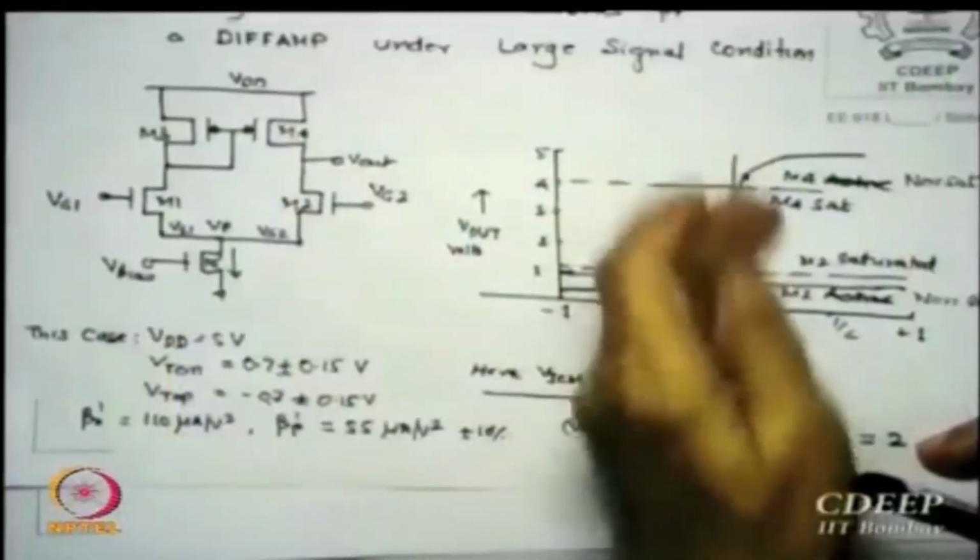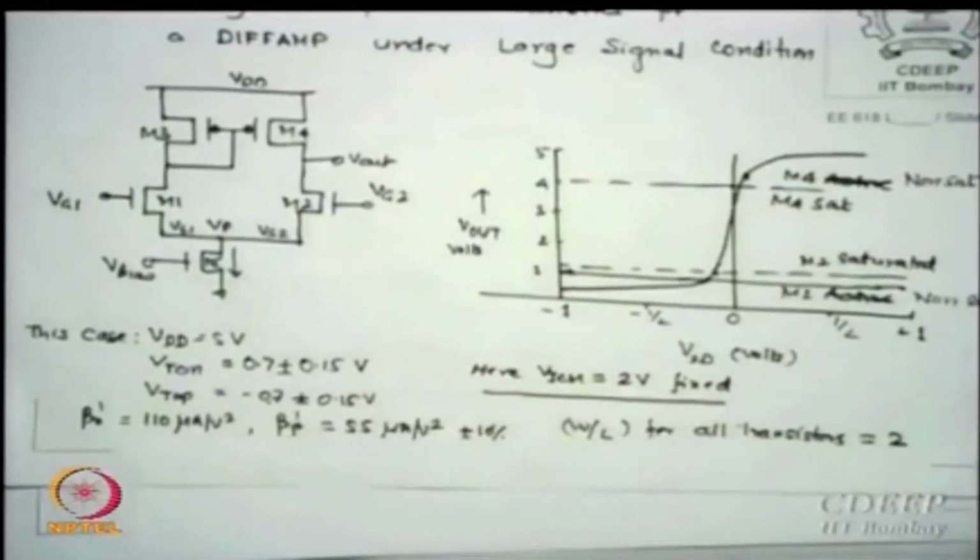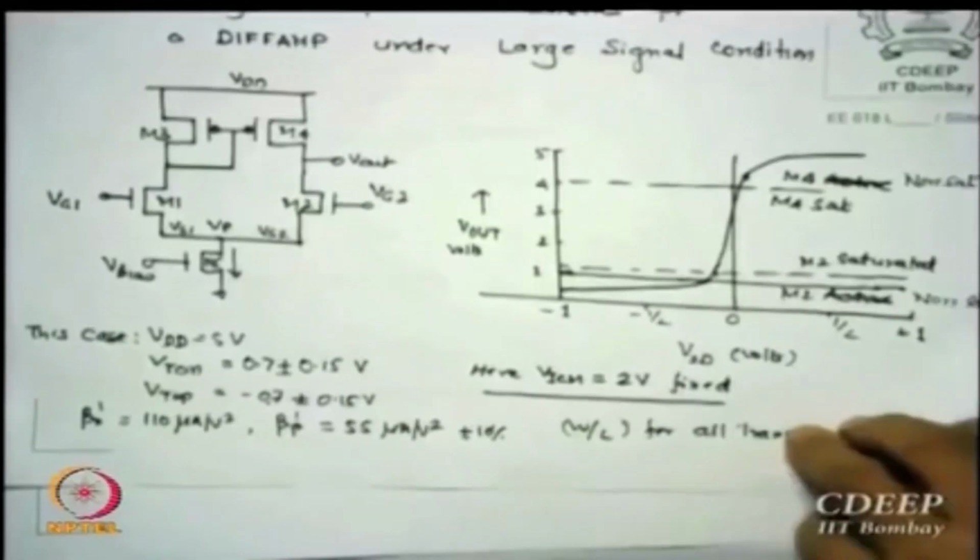Normally books do not put that term, they say only VICM, but I say okay, in case you feel it. The reason they do it is because the transition is occurring very close to 0, and that is why they normally neglect that VID by 2 term, but if you want to keep it, you can keep it, but it is smaller than other values, so it will automatically be numerically neglected, physically maybe accepted. Is that okay now?